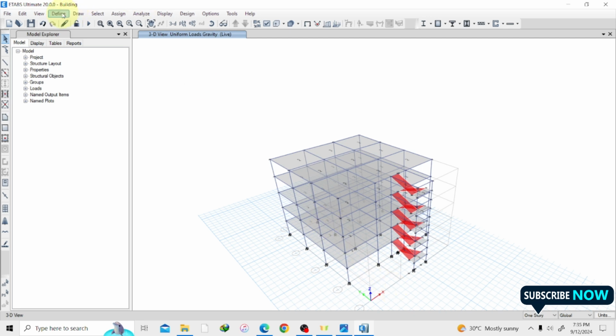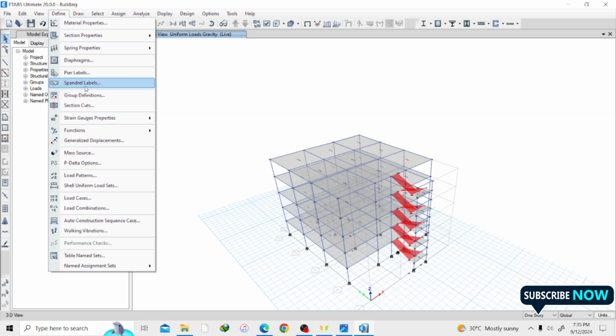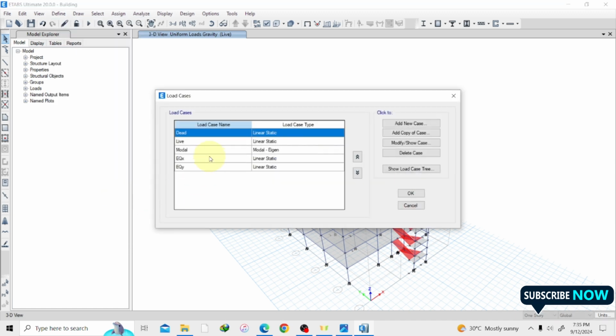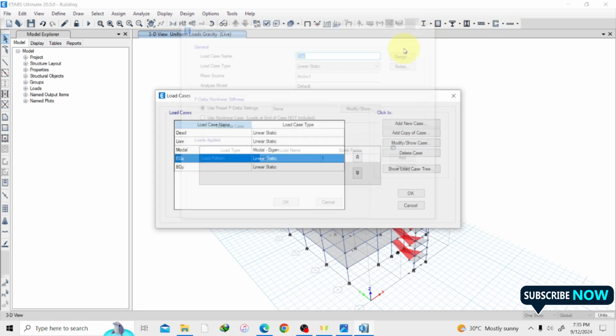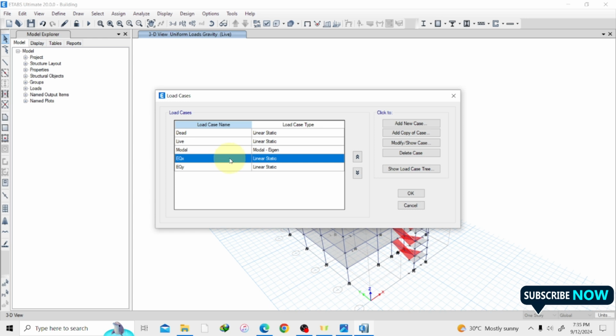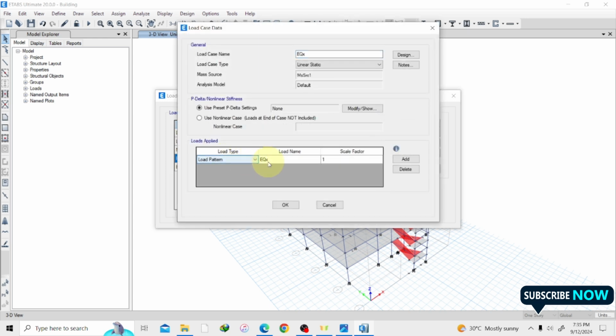So for the value we have for the x direction, you can also just negate them and get another x direction. So we can just come to load cases. We have our earthquake here, so you can just double click on that. So let's come here. Here, just look at the factor. The scale factor here is 1.